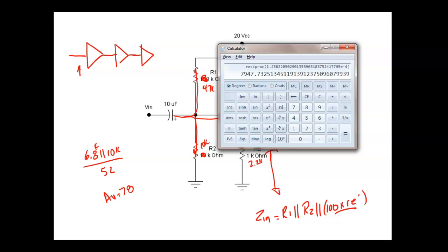Keep the gain lower. The gain is a lot lower. So we went from a gain of 3 to a calculated gain of 75. Measured 56. So that's a lot of difference. So the input impedance more than half, right? You understand that? So you've got to understand something is feeding this amplifier. And the lower the input impedance, the more power the signal that we're trying to amplify is going to have to provide. So that's what I'm thinking.